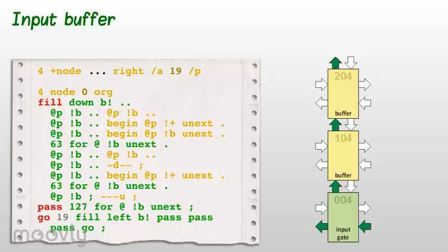Since port execution is extensively used, it is helpful to distinguish code executed by the node the code is compiled for from code executed elsewhere. Coincidentally, array4th compiler, when compiling F18 code, does not make any difference between green and yellow words. For that reason, we can use green or yellow words interchangeably. We employ this fact here using green words for code that will be executed in node 4 and yellow words for code to be executed at ports of nodes 104 and 204.